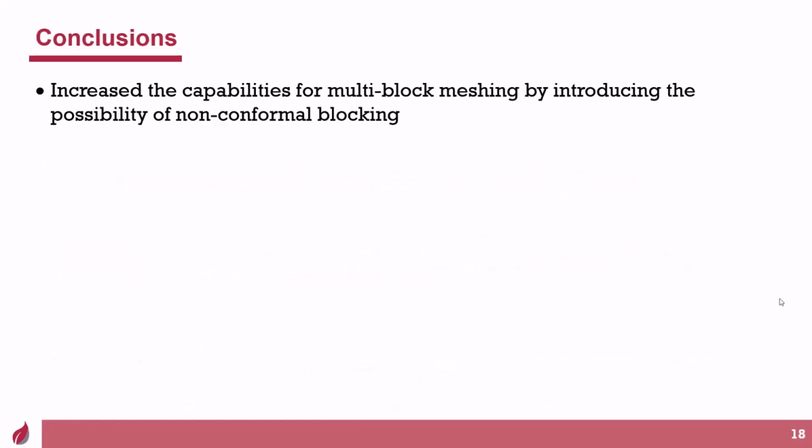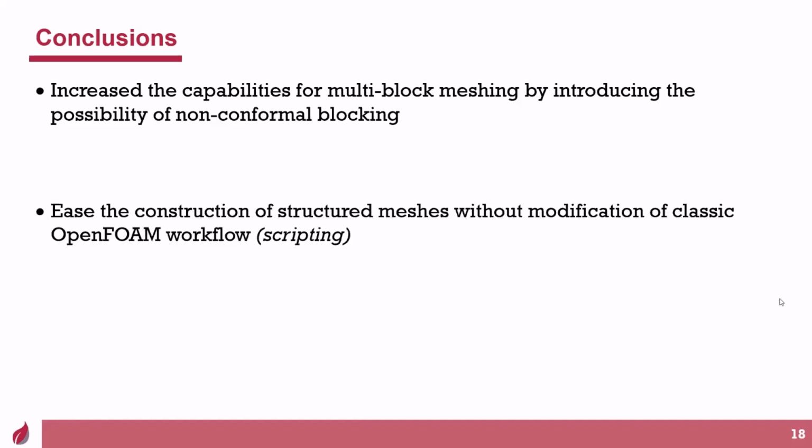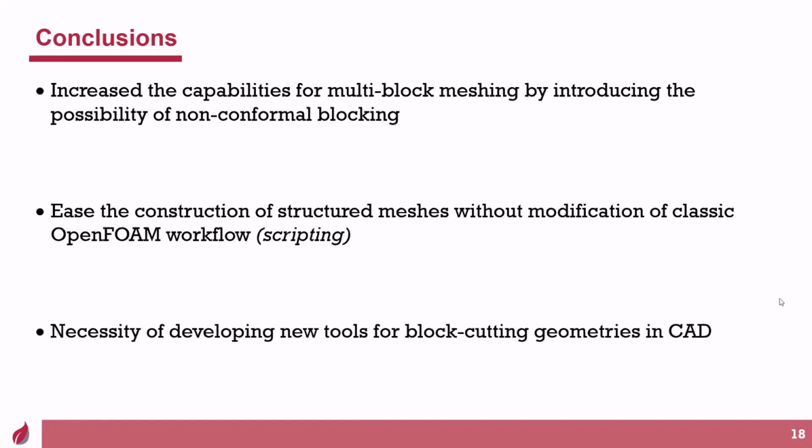In conclusion, I increased the capabilities of creating blocking geometries for structured meshes in open source tools, even with non-conformal blockings. This is going to help to apply them to OpenFOAM workflows, especially without changing the classic workflows where we use only text-based files. And we need to develop new tools for block cutting of CAD geometries.